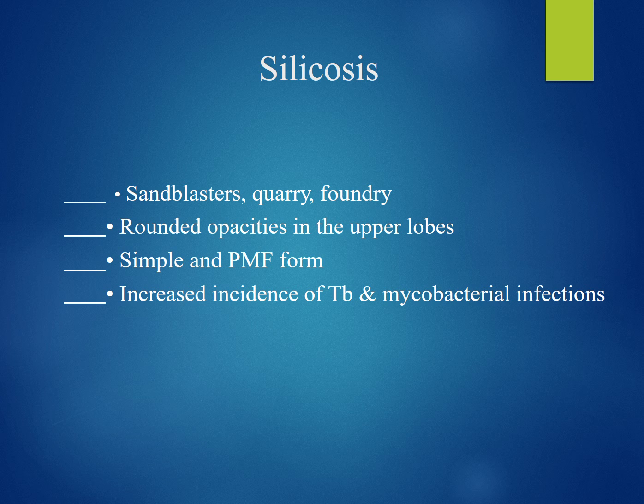There is a link on this page to a video from the 40s or 50s showing how to use wet methods to eliminate the hazard posed by silica dust. While this seems simple enough and has been known as far back as the 30s, we still see dry cutting of concrete, granite countertops, and pavers today.